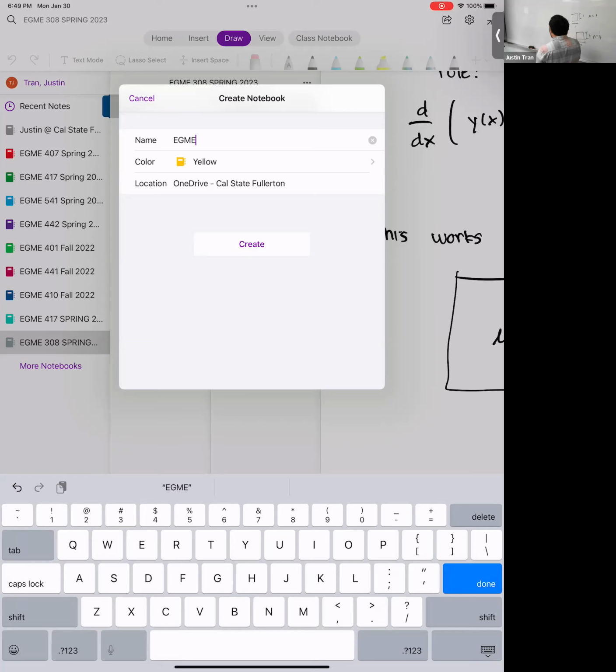And so that effect is magnified even more in 3D. Think of a cube, right? The volume of a cube, all the sides are 1, just 1. But if this is 2, the volume would be 8. And so that effect actually gets magnified. So what we did, where you cut the element size in half, is actually a pretty extreme change in the problem size. For 2D, it's not exactly 4x because there are other shape factors, so it ends up being closer to half of that. But for 3D, it's going to be 6 to 7 times. Yeah, that's exactly it.